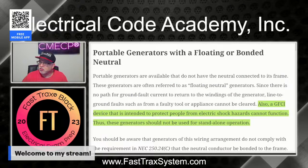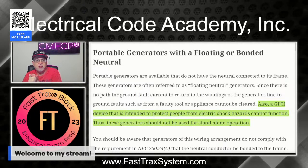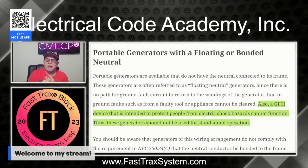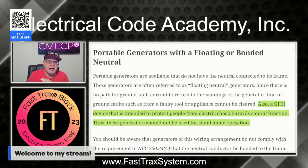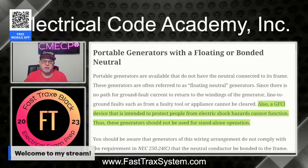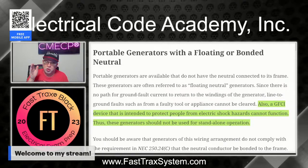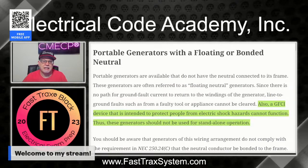Thus, these generators should not be used as standalone operation. So floating generators that do not have a bonded neutral to the frame, you do not want to use on a job site, construction site, maybe for your camper or something like that. You don't want to use them in those applications. If you're relying on the overcurrent device on that generator, or on that GFCI device to function properly, you do not want to use a floating neutral generator. You want a bonded neutral generator.